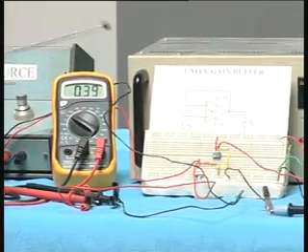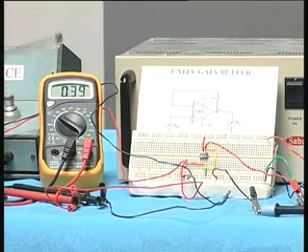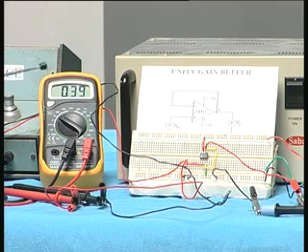So there is no gain, that is what you should recognize. But still you gain in terms of other features like the input resistance, output resistance and things like that, and therefore this unity gain buffer is a very useful circuit in a number of applications, for impedance matching and things like that.